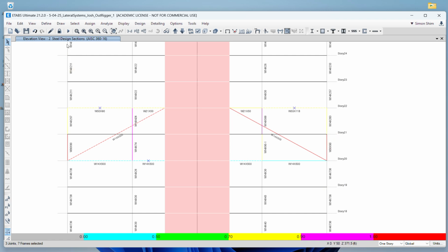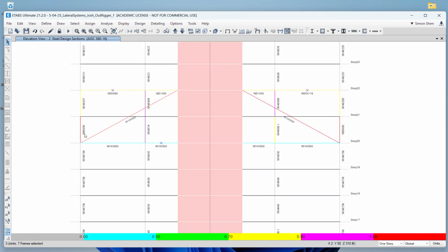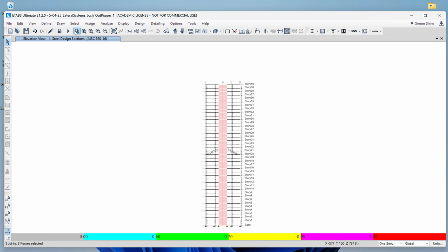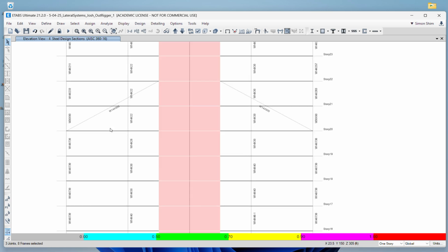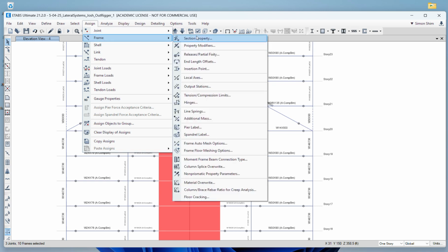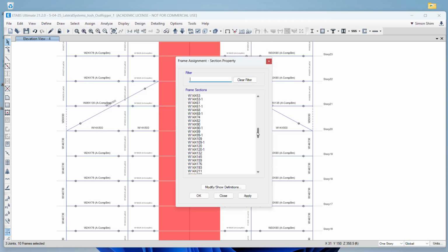So I think that's the first thing you have to understand, right? You mistakenly selected and assigned the W30 by 90. It should not be W30, this is the W14 series. So when you do this, you need to change the sizes. And the second one, let me double check what you did. If you have something wrong, obviously most likely you made a mistake. Here, see, this W30 by 90 is not the column section. So I'll choose W14 by 730.